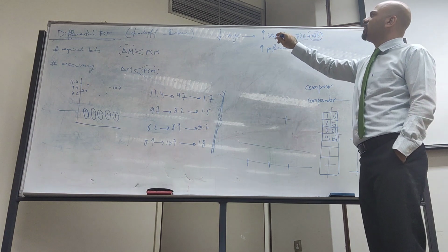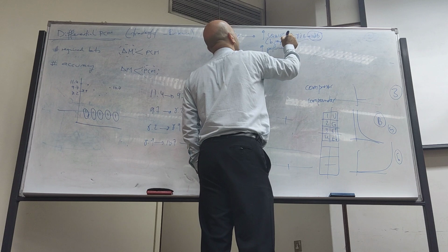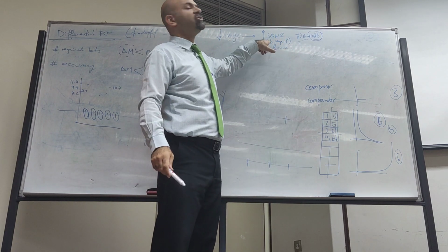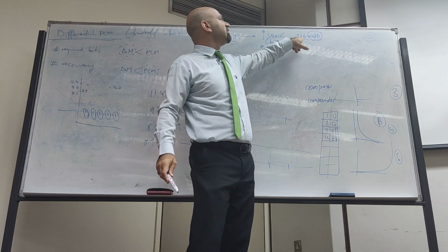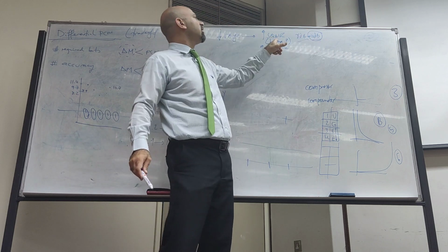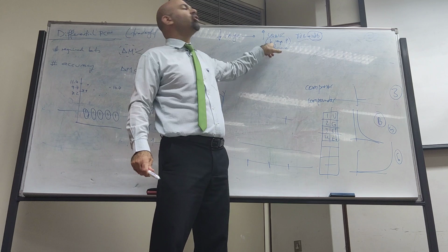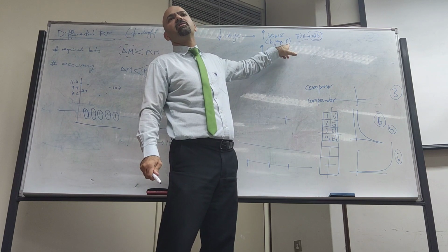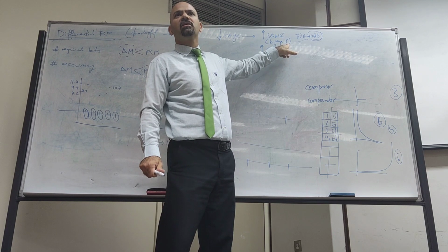In the SQNR, we have 3 parameters: the number of bits B, the range, and the signal power. So if you have increased the SQNR but you are still interested in 8 dB, you can put this improvement in terms of the bits, so you will need a smaller number of bits, or you will need less transmit power. Is the idea clear?